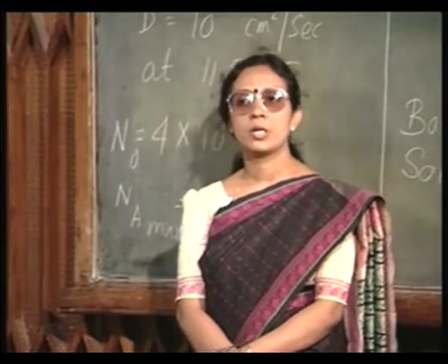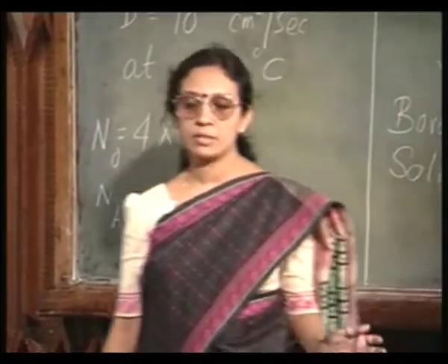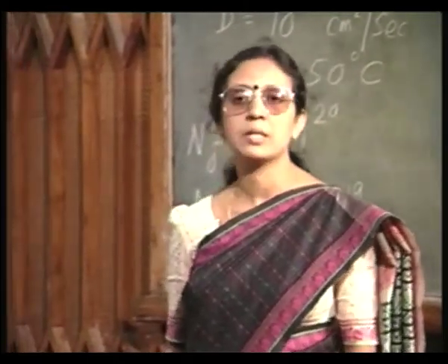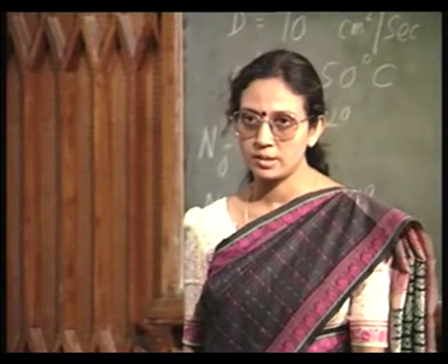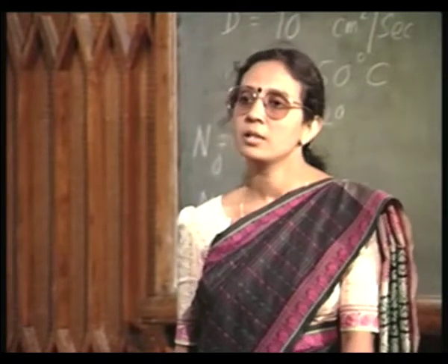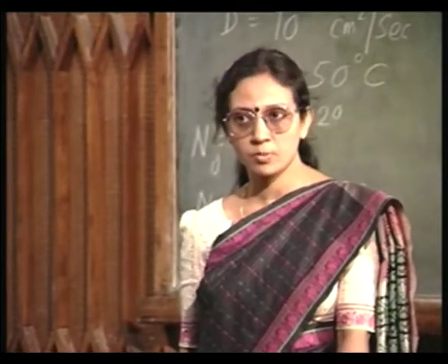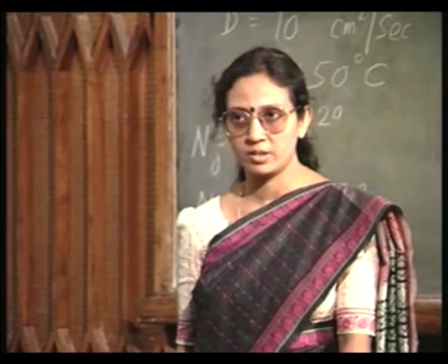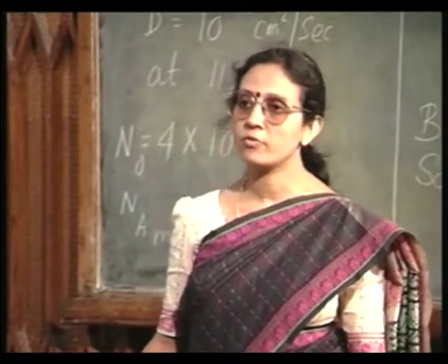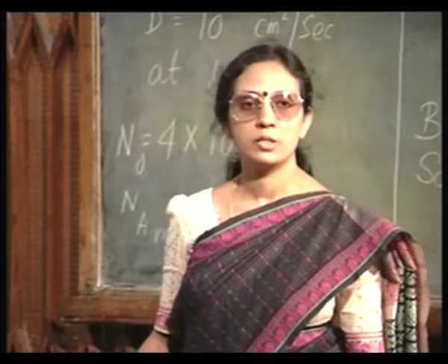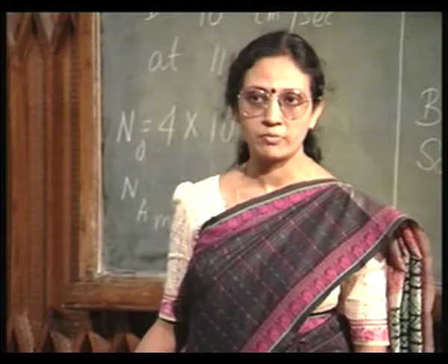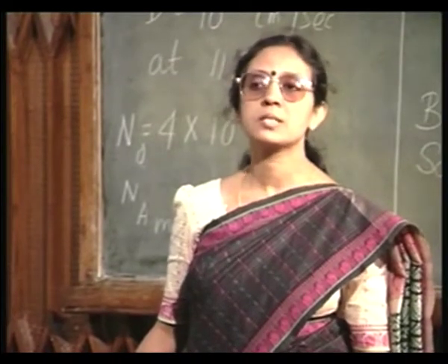So, this boron nitride first has to be activated, the temperature range is also specified for the particular type of boron nitride wafer, it can be anything between 750 to 1100 degrees centigrade. So, it will be mentioned, you know, it will be called say BN 975, then you know that the activation temperature of this particular boron nitride wafer is 975 degrees. Okay. So, you activate it in oxygen ambient, so that a thin layer of B2O3 is formed on the boron nitride surface, and then this oxidized boron nitride wafer is placed close to the silicon wafer,